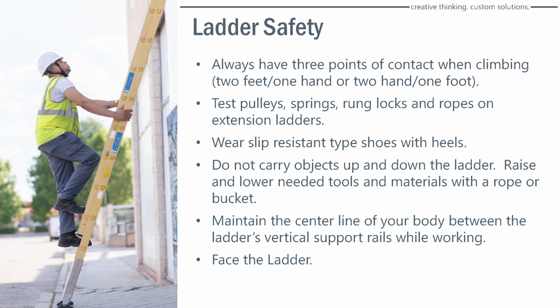Test pulleys and springs and rung locks and ropes on extension ladders. I like to say wear slip resistant type shoes with heels. Why the heels? So your foot doesn't slide through. Don't carry objects, like I mentioned. Maybe use a bucket or something like that. If you use a bucket, make sure it's rated for the amount of material you're going to put in. The canvas work bags are a lot better than a 5-gallon bucket you go buy from Home Depot. You put a lot of stuff in it, you start pulling up a rope, the handle comes out, now you got a problem.